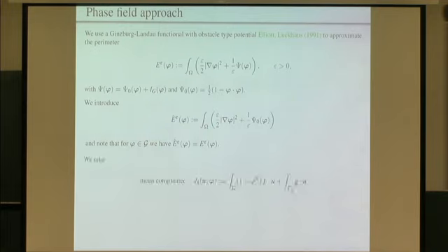In our phase field model, there are two objective functions that we consider. J1 is for our mean compliance. What we want is the force to act on the material regions, not where the void is. We recall that the void is associated with the order parameter phi capital N, and because the sum of all the phi i's equals 1, this 1 minus phi N will represent the material regions, not the void region.